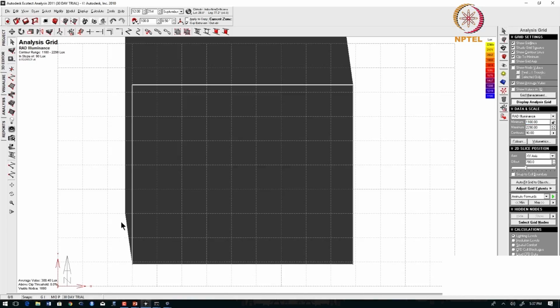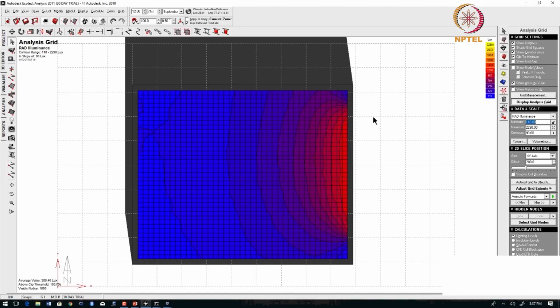So what is the takeaway from here is when we use different visual light transmissions, we can understand how much will be the average lux that is entering inside, and also understand the distribution of light. So here it is showing a small gradient where 110 lux is shown in blue, and as we go higher the maximum lux that comes here is in the range of 700 to 900. So you can see the color coding here, and it might go as high as 1000 lux level.